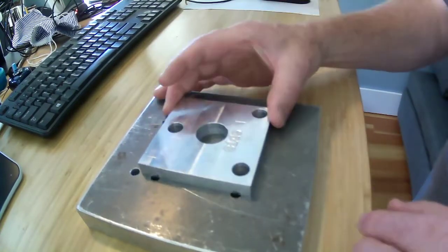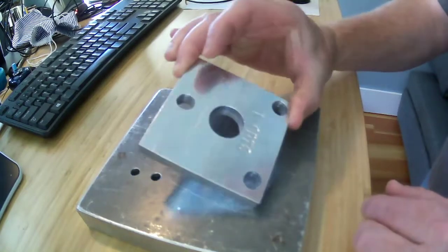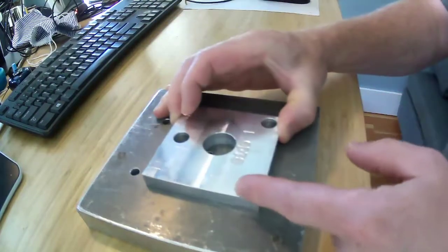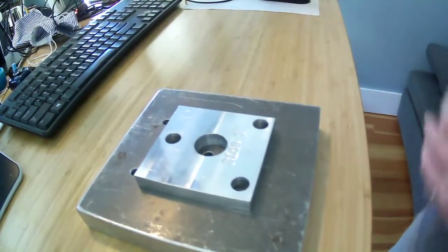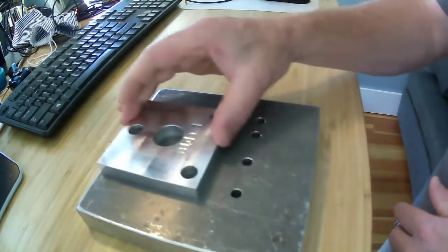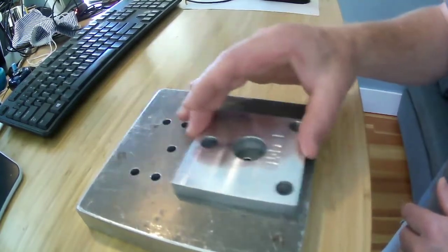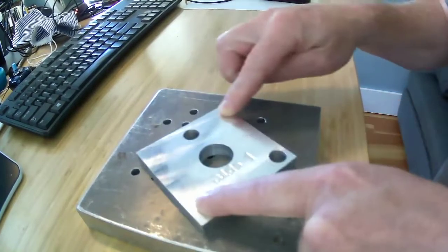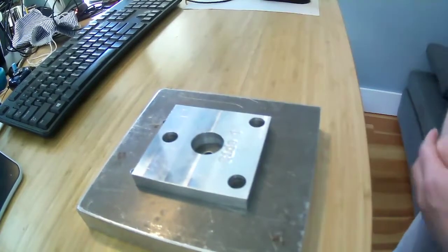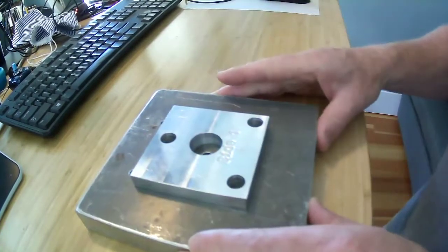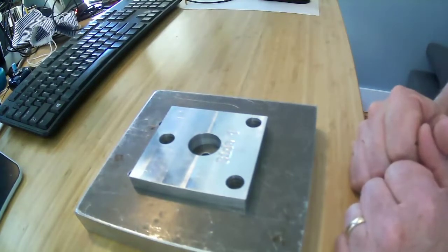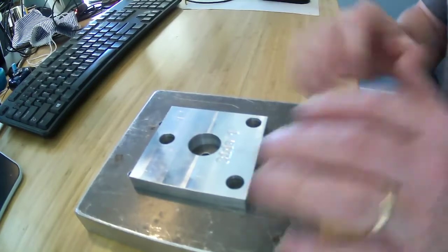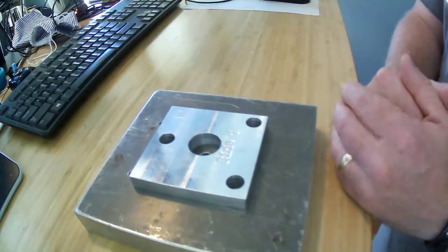It turns out that it also can't rotate around this axis or around this axis anymore when it is down on the part. So it has eliminated 3 degrees of freedom. What 3 does it still have? It can slide in y, it can slide in x, and it can rotate around z. So we've eliminated 3 degrees of freedom, but we've still got 3 degrees of freedom. Okay, so what we need to know is, we eliminated 3 degrees of freedom when we put these two together.